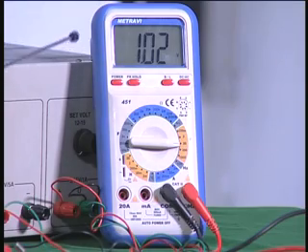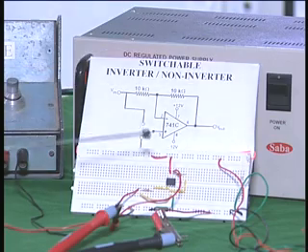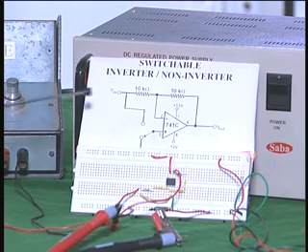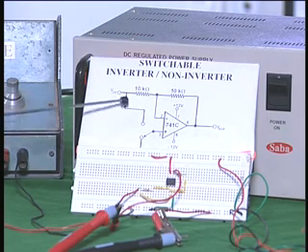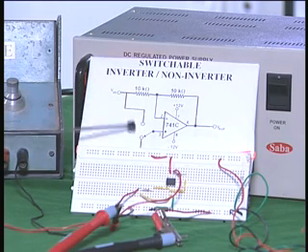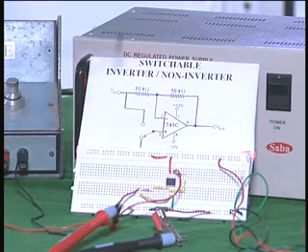Previously it acted as an inverting amplifier with a gain of -1. Therefore I am able to switch the amplifier to non-inverting or inverting by just switching this wire between the ground and the input. That is all I wanted to show you. So we have seen the very simple demonstration of the switchable inverter and non-inverter circuit.